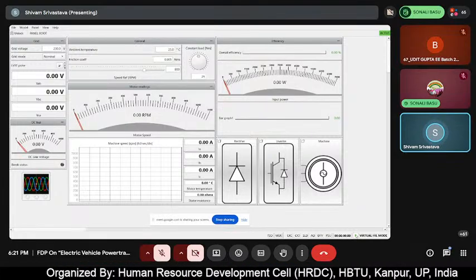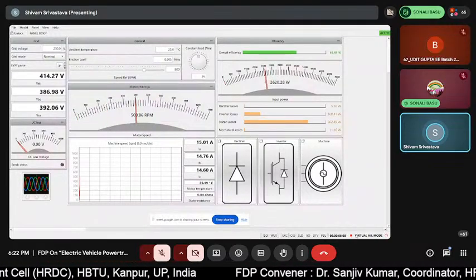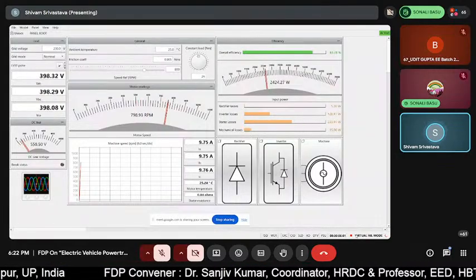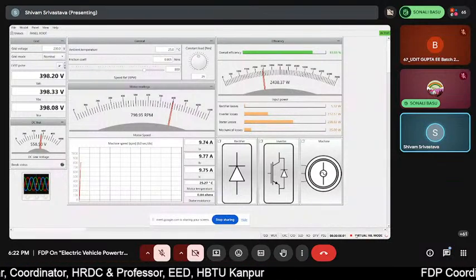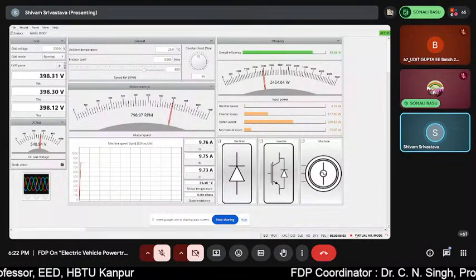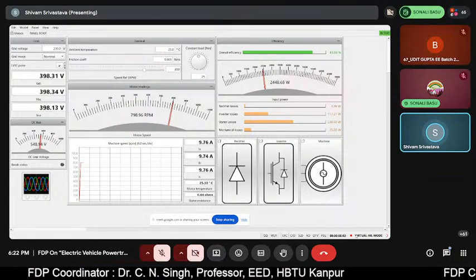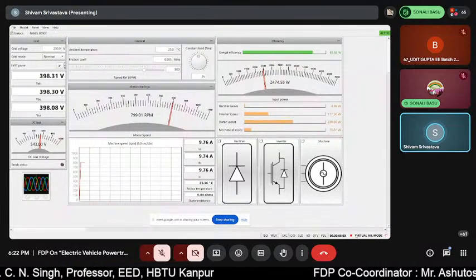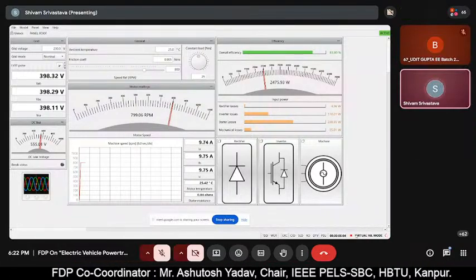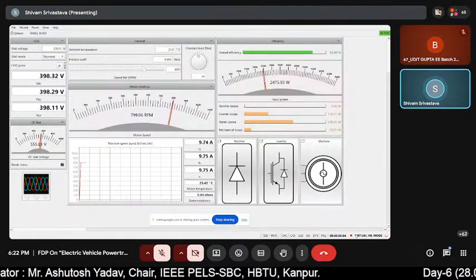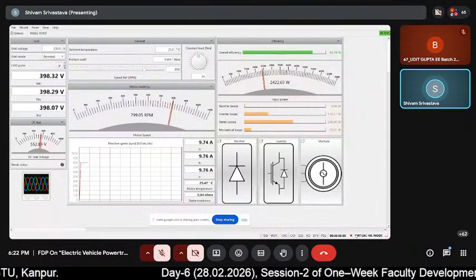I'll quickly run this model, and you can see there are different tabs available, starting from the grid section, where the voltage, grid mode, LVRT pulses, the phase voltages VAB, VBC, and VCA, the DC link bus voltage, and the braking status are shown, along with the ambient temperature, friction coefficient, speed reference, constant load value, machine speed, machine current, motor temperature, rectifier losses, inverter losses, stator losses, mechanical losses, overall efficiency, and input power. All of these we can observe.